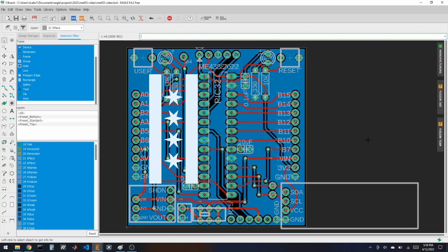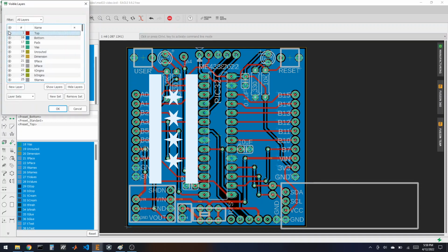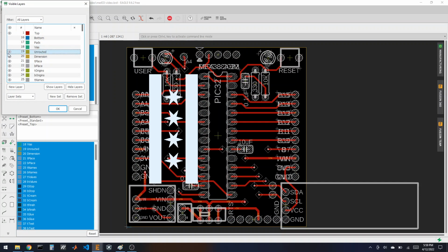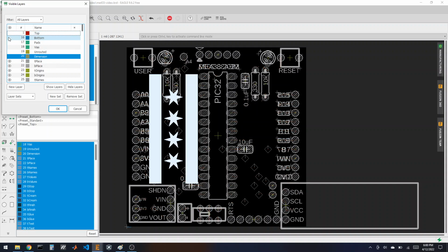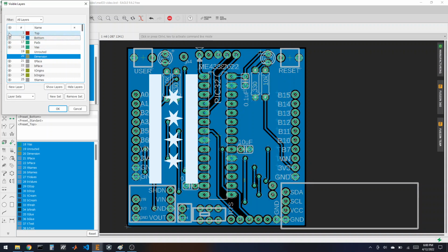And that's designing PCB. So try to upload your Gerbers. Make sure it looks like this. I like to sit on this for a day or two and come back and look again. It helps to turn layers on and off. So for instance, we'll turn off some layers just to see the red, and then turn that off just to see the blue, and think about pins that you haven't used yet.